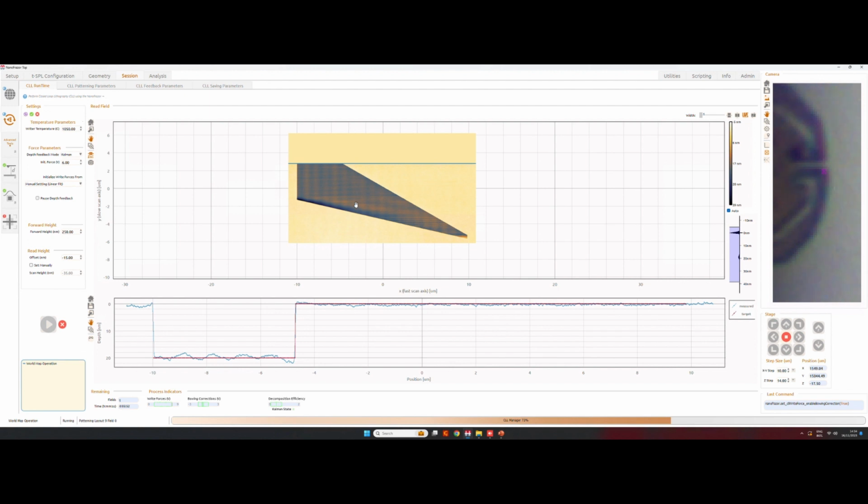I would say it's important to recognize when we can use the bowing correction to improve our patterning, and also how these two, bowing correction and prediction, act on the cantilever. So they modify the voltage that we apply to bend them in order to correct this change in capacitance.